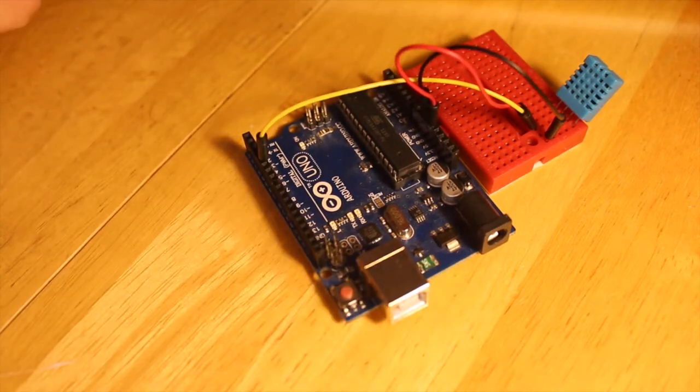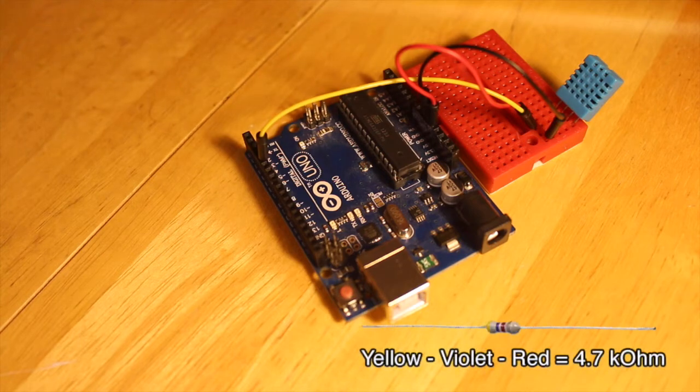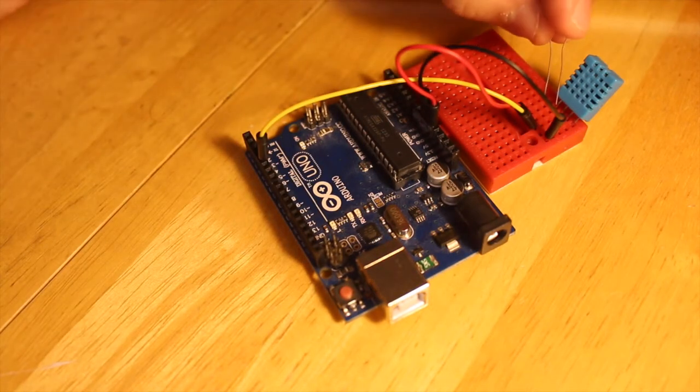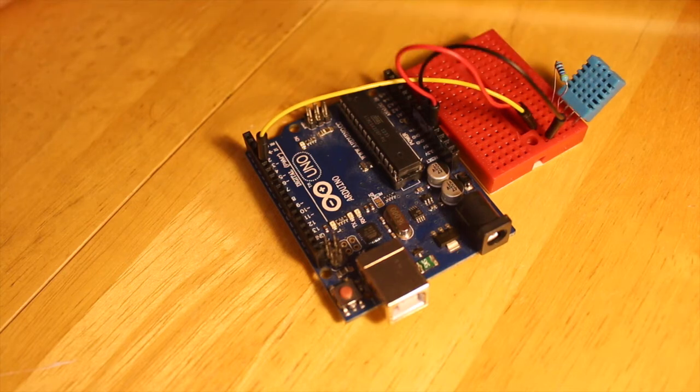Okay, just one thing that we need to remember is that we need to connect a resistor between the first and the second pin. So I'm just gonna get my resistor here, and I'm going to connect it between pin 1 and 2. Okay, let's go. Perfect. After we have all this connected, it's time to test the code.